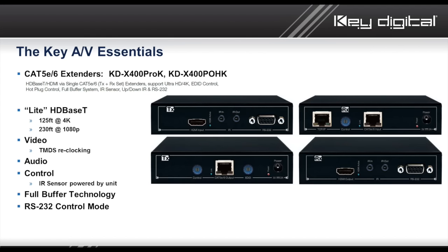So if you didn't like what you just heard from me, which was get yourself that USB to serial adapter, get yourself a female RS-232 to 3.5 millimeter that KeyDigital can sell, that you or your guys can fabricate, that is sold at a basic computer supply store, if you don't like that I told you that, that's fine. Purchase the 400s instead of the 200s.